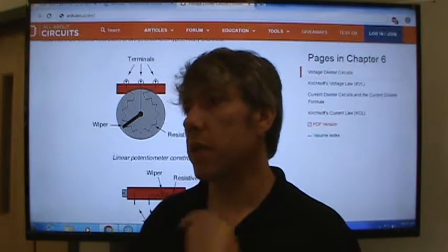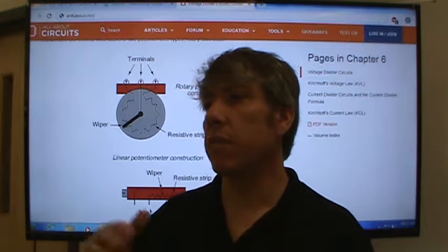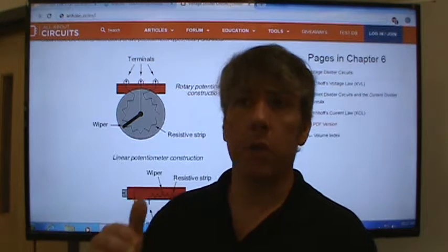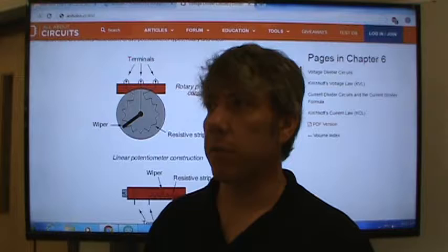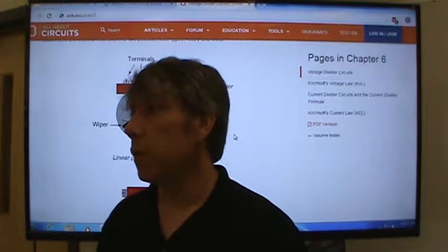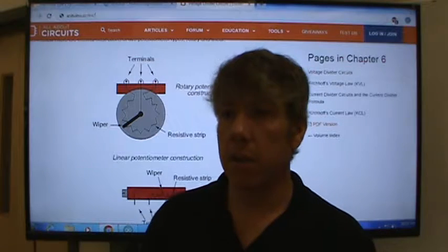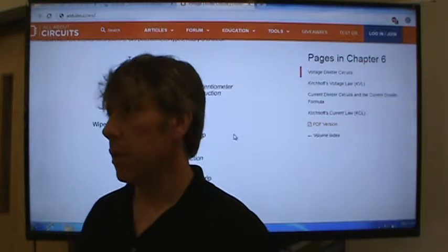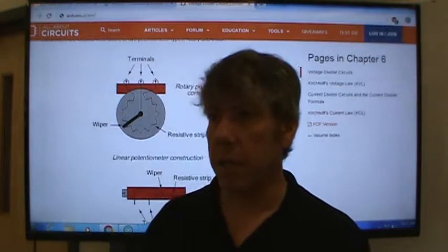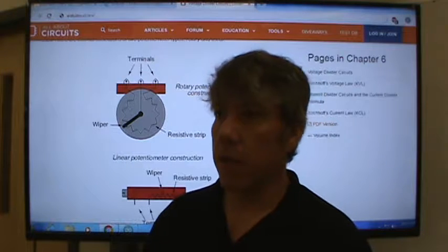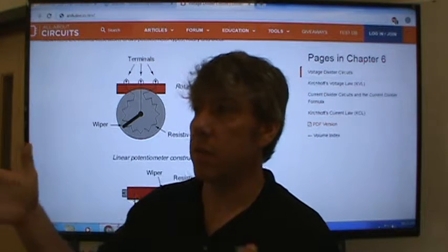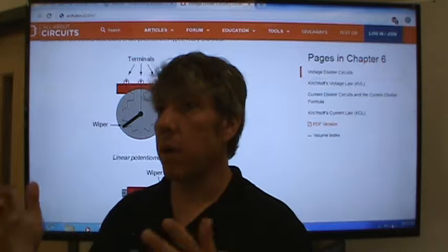And so what it does is it basically samples the signal. A minute ago I said 0 to 5 volts, 0.1, 0.2, 0.3. Well, could it really have that level of resolution? It depends on how many bits are used. Because when you read an analog signal, you've got to give it a number in the Arduino, not an on-off status, right? So if you're going to give it a number, you have to know how many bits you have to work with to represent the number.